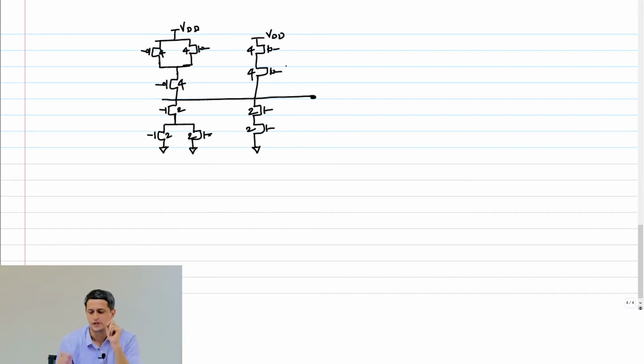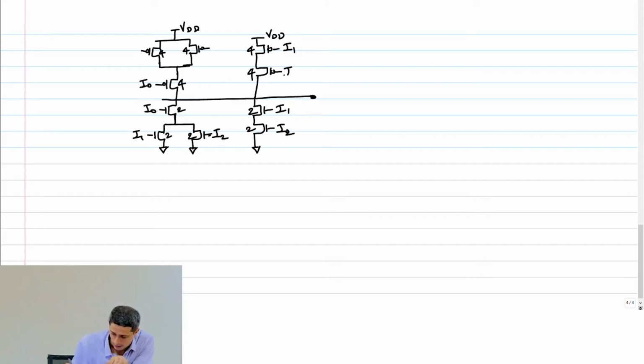First, tell me the logical effort of, let's say this is my input I0, I1, I2. Okay, so this is also I0, I1, I2, I1, I2. What's the logical effort of I0? G I0. How much? 2, right? 2 plus 4 by 3. What's the logical effort of I1, I2?